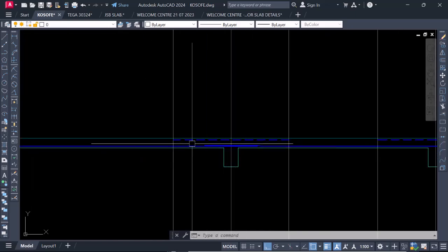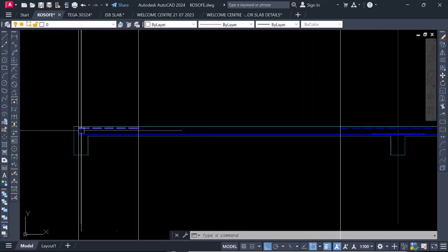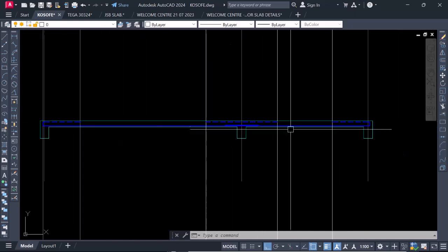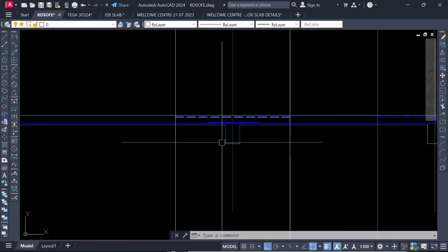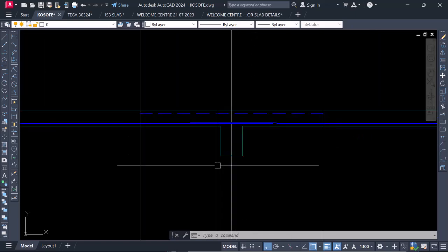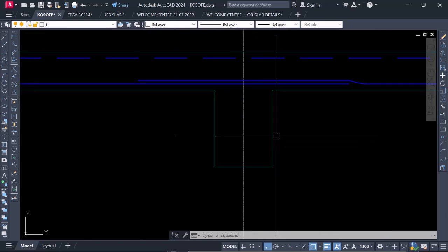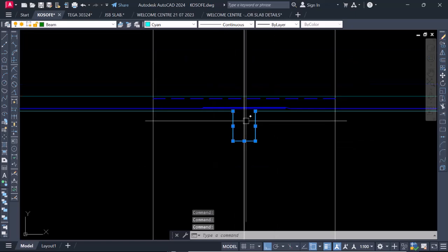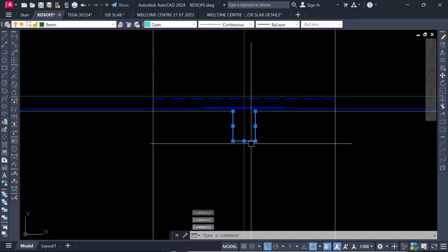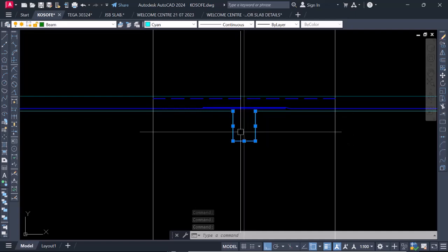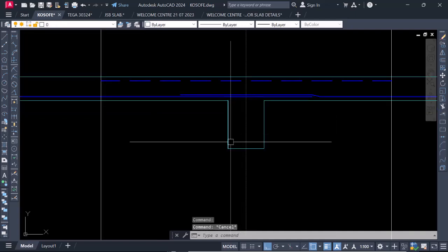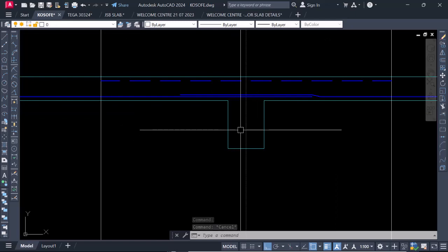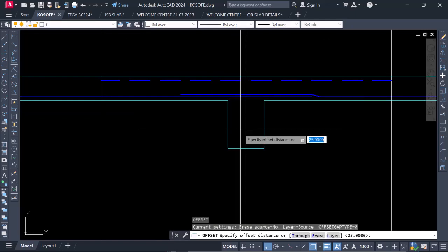You can see. So the next thing we're going to do before we drop our floor reinforcement, before we drop all our reinforcement along this region, what we're going to do right here is to cut the beam section. Let's cut this beam section, all right? So before you cut the section, you're going to look at this is your beam, our drop down beam. So we're going to look at what will be our concrete cover in the beam, right? What will be a concrete cover? So let's say we are having 30 from this beam, having 30 to be our concrete cover, right? So we're going to offset 30 millimeter.